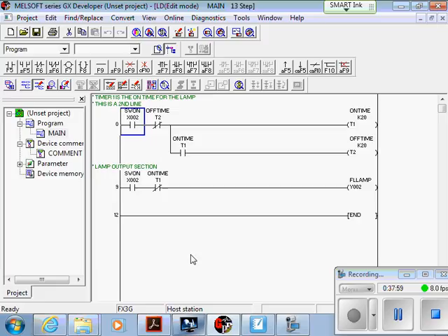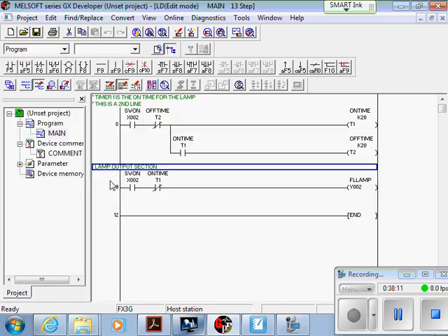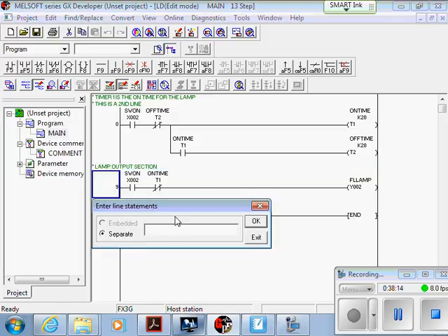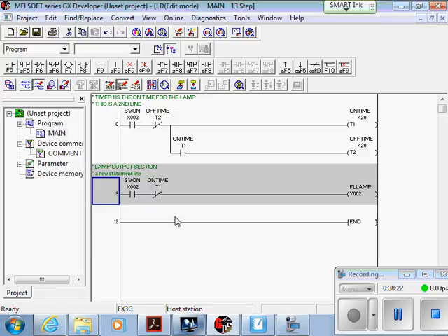And then lastly, we've got the statements. If we turn the statements back on, they are the multi-line explanation of what the ladder rung does. You edit them in statement write mode, and I double click here, I can put a new line in like so, and I can have multiple line statements. Yep. So there, in last week's notes, like I say, there's a step-by-step exercise that takes you through all of those steps on that program that was the solution to the double coiling problem that we went through last week.